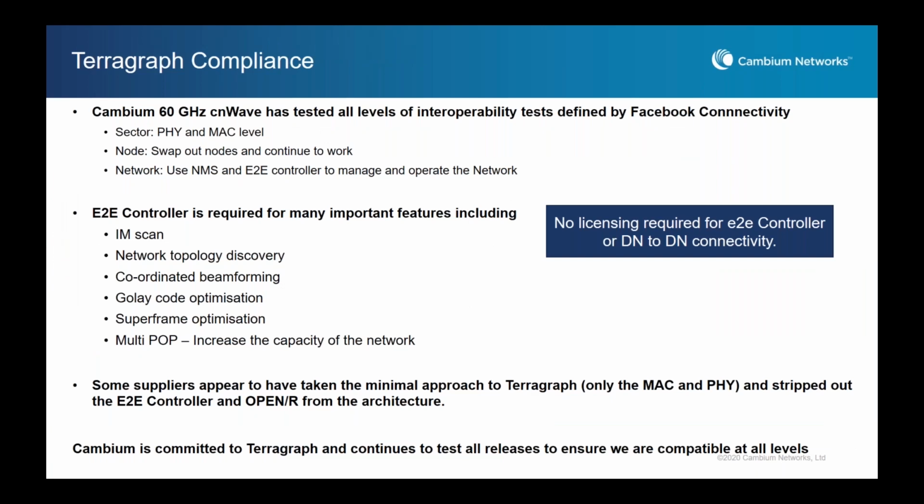Okay, so Bruce mentioned a little bit about Terragraph compliancy. Why are we so interested in Terragraph compliancy? Just to let you know, Terragraph compliancy is at 3 different levels. It's not just about the MAC and PHY, which is the chipset level. That's great, that gives you your TDD synchronization. It gives you your automatic transmit power control and things like that. So that's good. But it also comes at different levels, such as node level, where in theory you can swap out nodes for different vendors if you wanted to go that way.